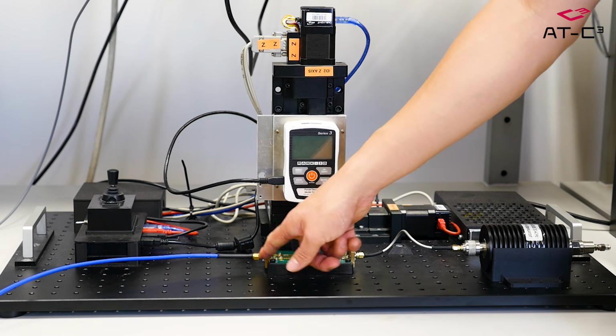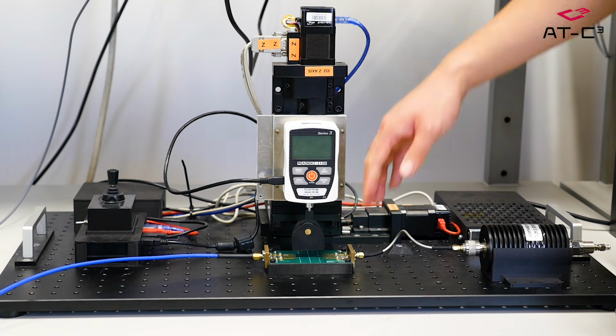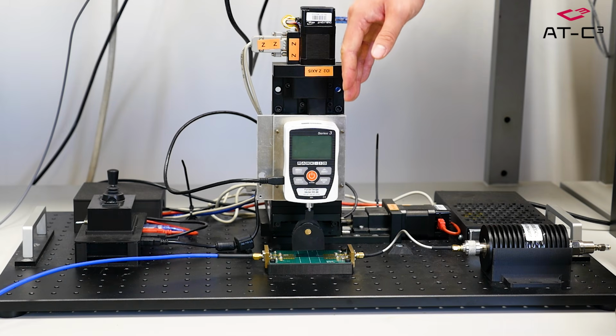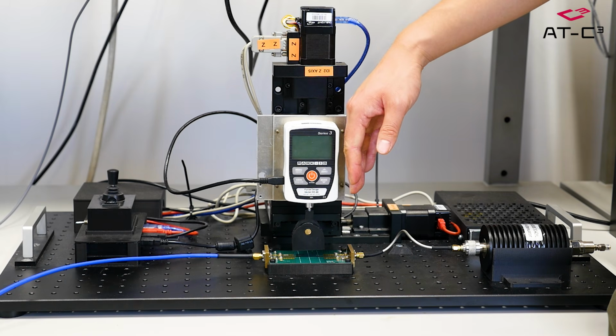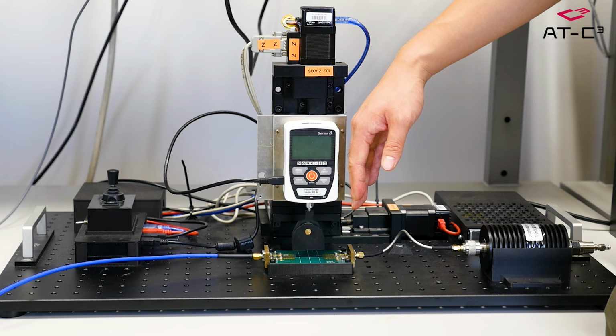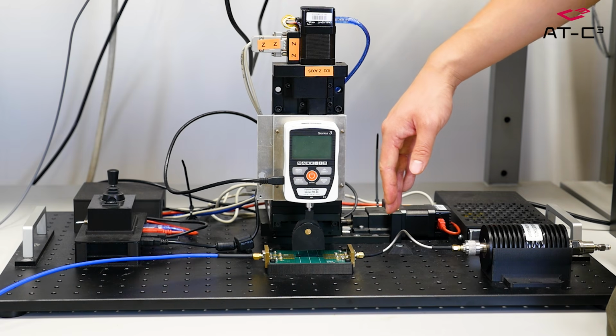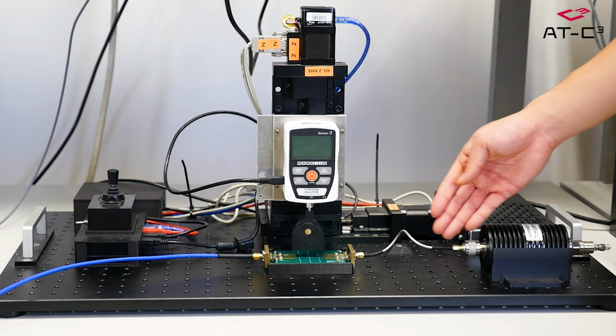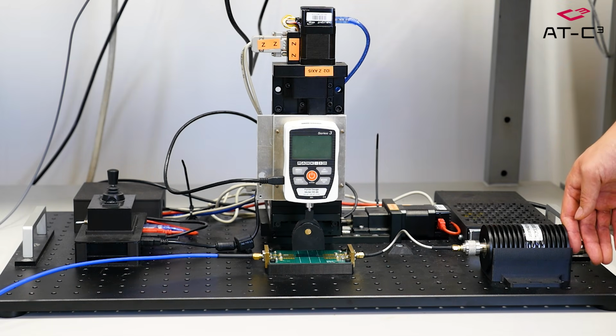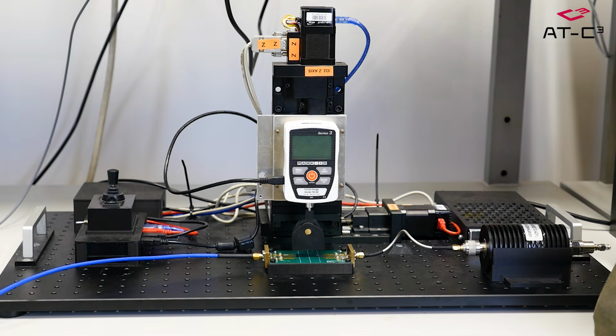Once the signal is sent out into this PCB, the robot arm is controlled by the computer to keep pressing down. While pressing, we keep recording the harmonic reading and the force gauge reading simultaneously. In the forward direction, we terminate our signal, and we only measure the reflected harmonic in this case.